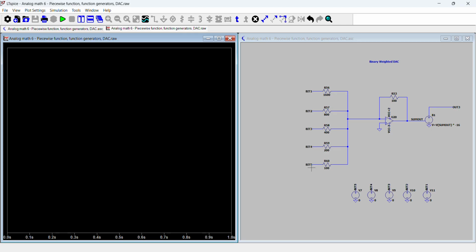And this is basically a binary adder now, right? Because this represents exactly what binary values are for. For example, if you have 0, 0, 0, 1, that's just 1 times 1. And then if you have 0, 0, 1, 0, that's 2 times 1, etc., 4 times 1, and 8 times 1, and 16 times 1. So that's exactly what this is doing. It's outputting a binary weighted voltage and summing it up and then amplifying it back out again.